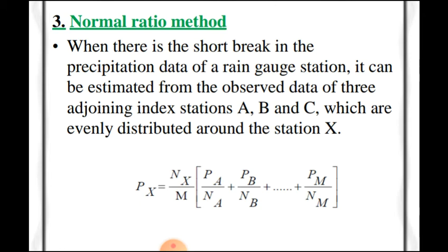Typically we say that rain gauge values depend on rainfall over a particular location. This kind of equation tells us that for any given duration the average depth decreases with area. The values k and n depend upon the catchment area. Some typical values are given in various textbooks for different areas.